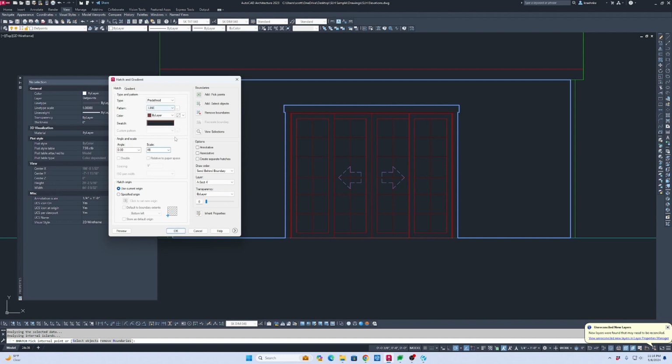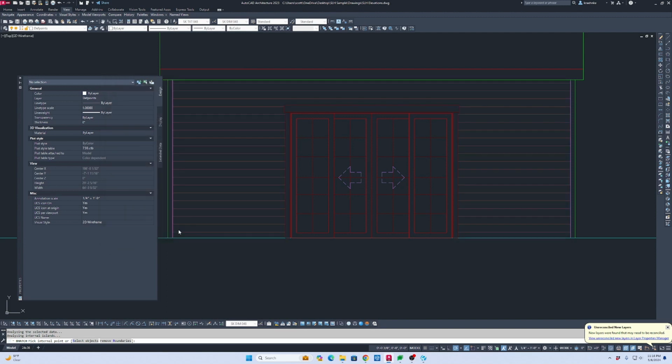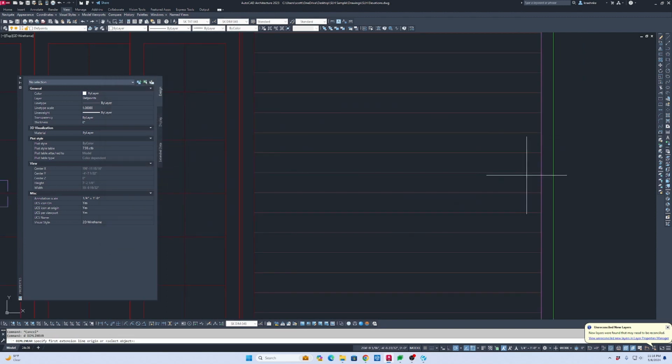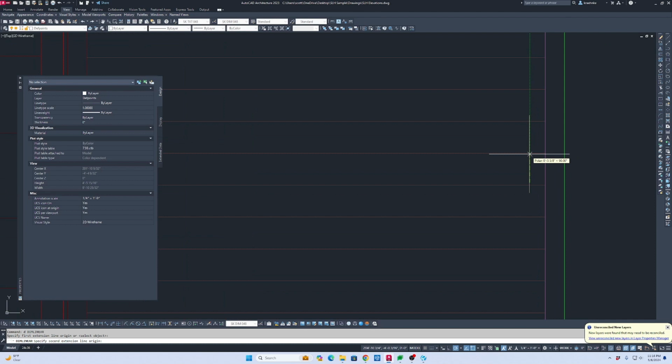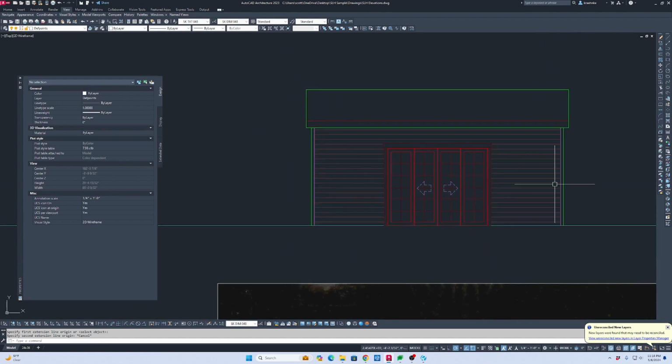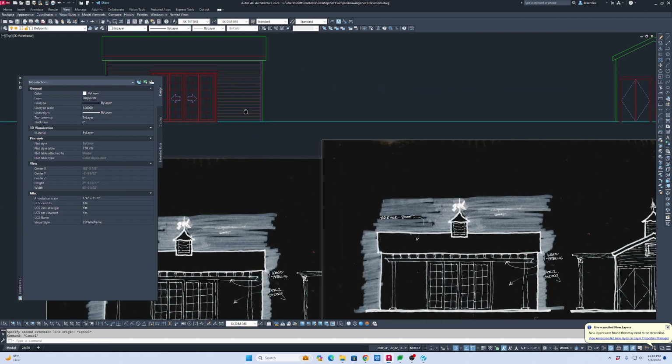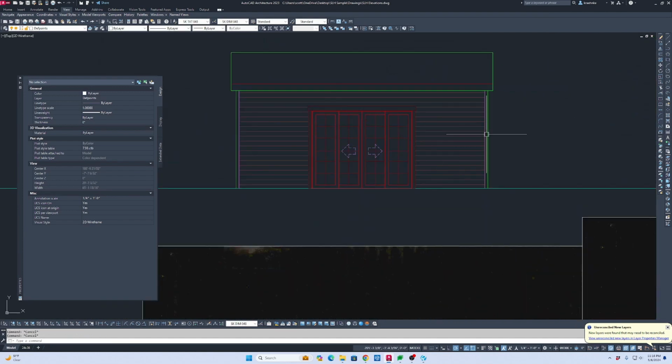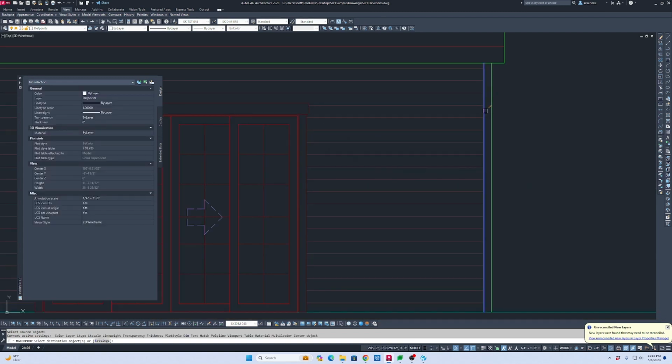I know that because this line is 1/8 inch for 1 scale. So let's just double check. I didn't snap to it correctly. I don't have my snapper hatches on, so it's going to be close. Yeah, those are 6 inches. That's believable. I like that. Oh, it's on the wrong layer, though. I'm going to put that on hatch 1.